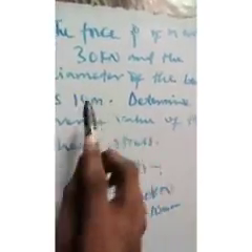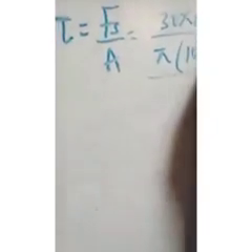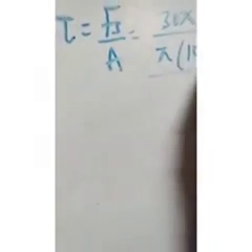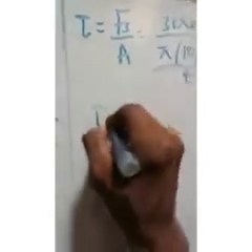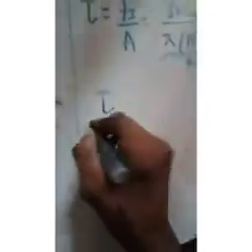Now, in a case whereby you have it as 10 meter, you simply have your diameter as 10, and that will be pi d square over 4, and I can solve and then I'll have my top. Now to find the half value of this shear stress, that will be divided by 2.